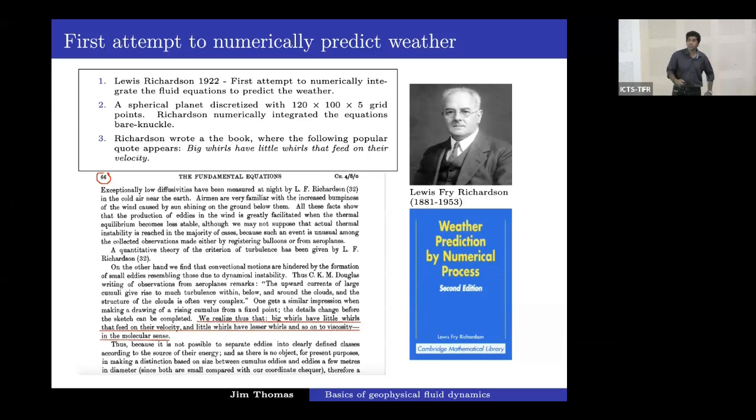People who work in numerical simulations know this. You have a permissible time step for integrating equations, which is set by what is called a CFL condition. If your time step is larger than what is allowed by the CFL condition, your simulation will just blow up. So Richardson's simulation blew up, but he explained the whole procedure that he went through and all his thoughts in a book, which was written based on his failed attempt.